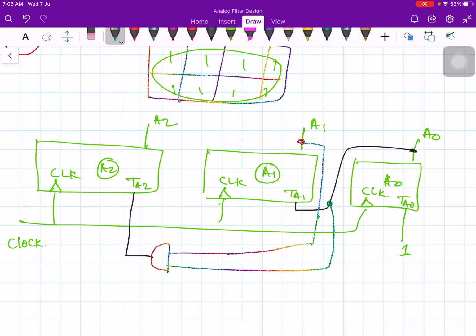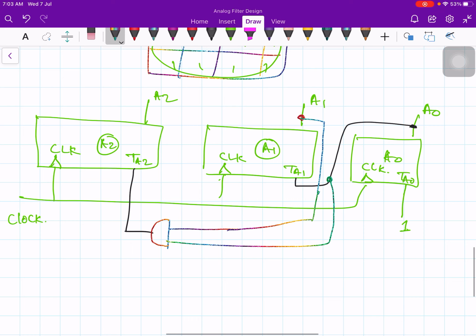Therefore I have 3 input equations. With those 3 input equations I can construct the binary counter using T flip-flops. Using these functions with these 3 flip-flops we obtain the logic diagram of the 3-bit binary counter. For simplicity the rest of the signals I didn't show here. Actually when you design a counter, the counter must include signals called preset and clear. I did not show them here, but it must have preset and clear. So that's how one can design the counter using T flip-flops.